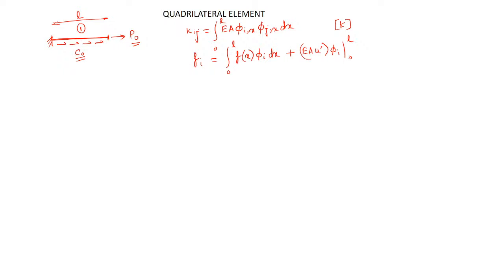So now let us go ahead and solve for this problem where the whole domain has been discretized with one element. Alright, so the first step, as we all have understood till now, is first we have to define the shape function. So how to define the shape function? If I look at phi I, how it looks, it is 1 at this point and linearly goes to 0 at this point. So this is node 1, this is node 2. I have defined like this because the whole domain I have taken as one element.